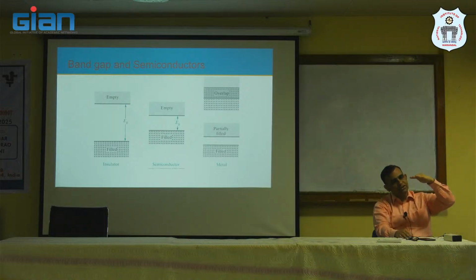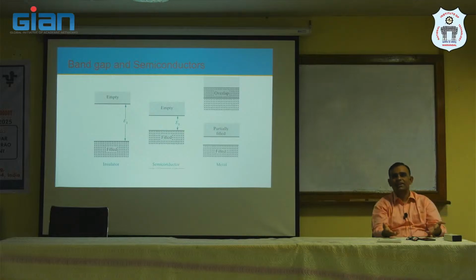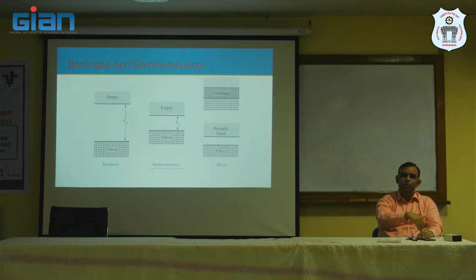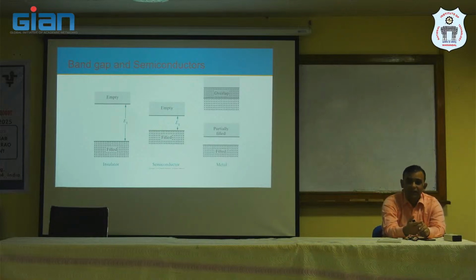That is the depth in the structure. Photons are coming with an energy, so they try to penetrate the material. At some penetration depth, do they pass on their energy? Because infrared photons have decent energy, they try to go deeper, so their penetration depth is higher than, say, ultraviolet photons. So if you make a structure which is very, very thin, even though its band gap will be fine, a large number of photons will pass through.